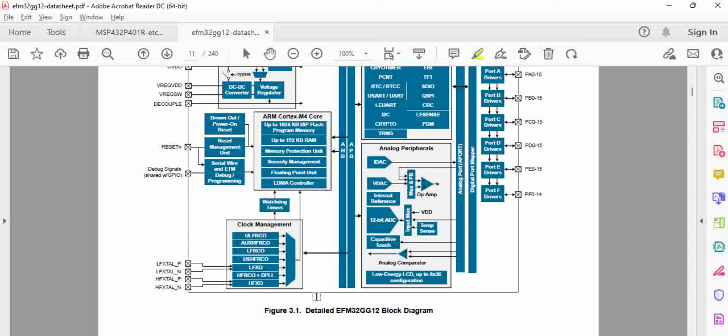But if you need a stable clock, and yours is a very time critical application, then definitely you go for an external clock. That is the basis for whether to use an internal or external clock. To put it the other way, the internal clocks of microcontrollers available in the market have a very high ppm variation per degree centigrade. That means based on the temperature, the frequency is going to vary slightly, which is not desired, right?